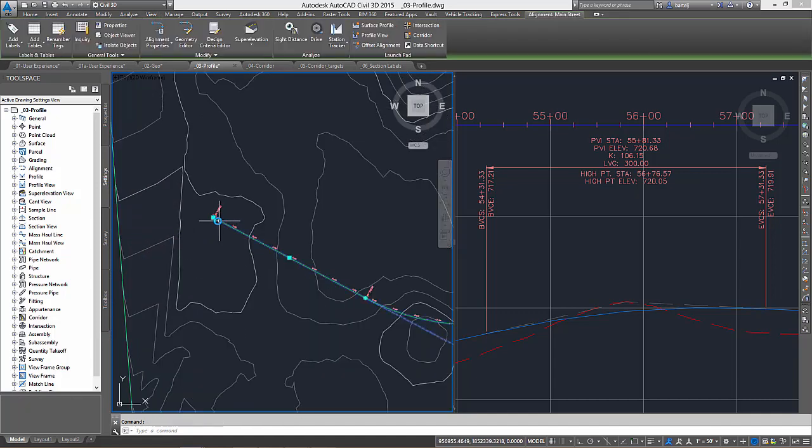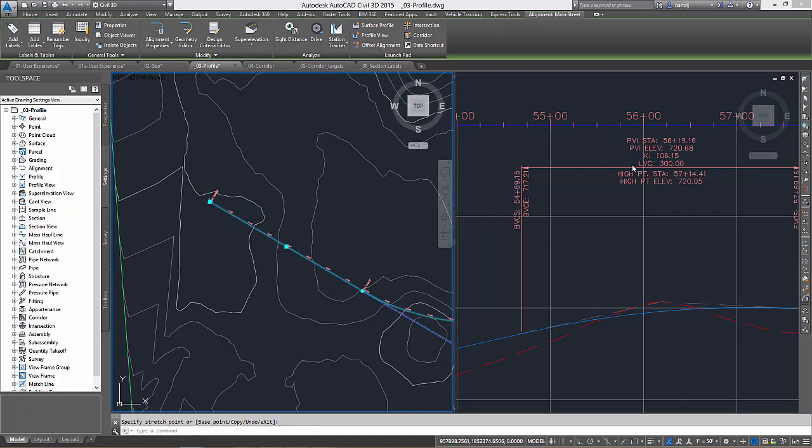Once again, if I were to make a change at this point and move it, say, from here to here, the impact of my proposed change is not going to alter maybe the proposed roadway at that point, but it will affect how it matches up with the existing. So if you think about it, my new existing profile will shift. I would expect my proposed geometry that is now locked to the horizontal alignment or that location to also shift. And when I pick, you see it updates, it continues to move down, and it remains tied exactly to that same point.